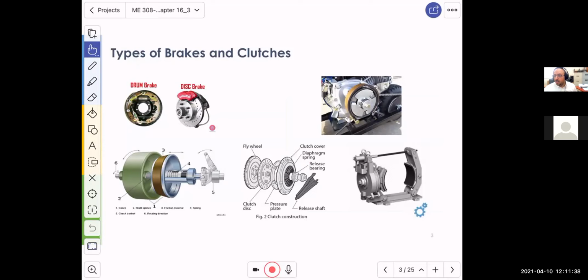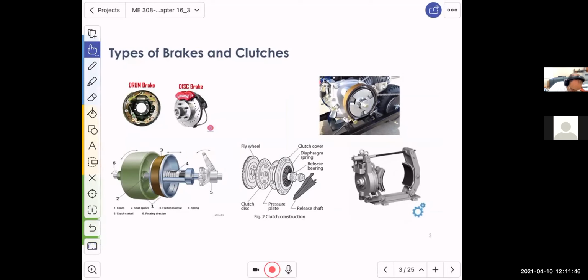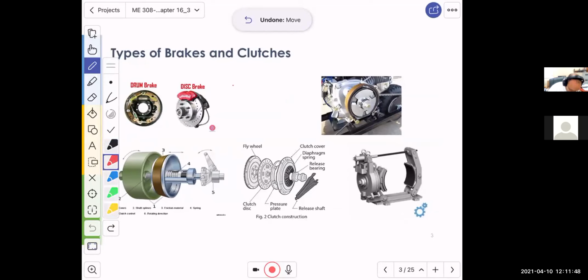Now, these are some examples of brakes. As we said, we have the disc, as you see over there. Sorry, this is the ABS, and this is the drum. The drum has multiple shoes, and these shoes expand, and when they expand, there is a pad, which is the braking material, the frictional material, and basically brakes help dissipate kinetic energy. These are too common.